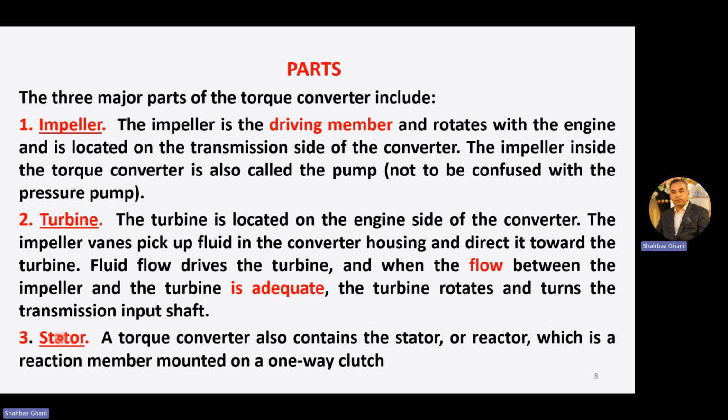Now the third part is the stator. A torque converter also contains the stator, or reactor, the third part, which makes it different from the fluid coupling. The stator is a reaction member mounted on a one-way clutch. We will see this.